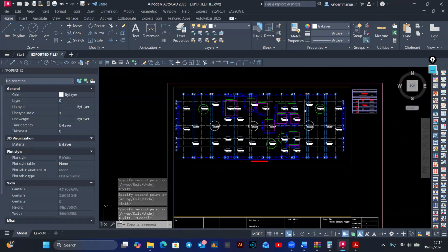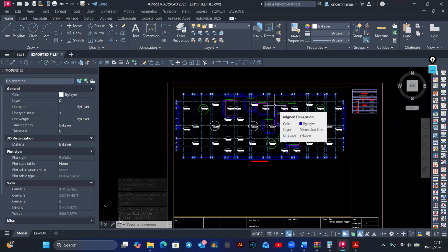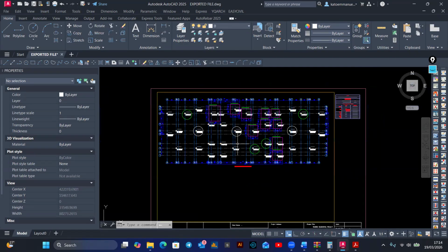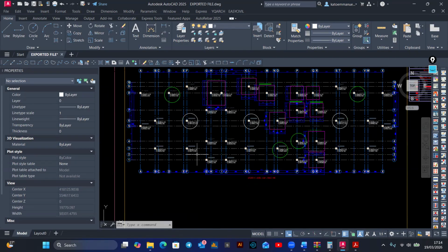So when you are designing your footings in ProtaStructure, you do not design all the footings for the entire structure. You look out for the axial loads that you have grouped. For example, this is green, green, green, green. You look among the greens for the column with the maximum axial load. That is the one you identify and design that footing. Then you assign that footing to all those which are green. You get it. Likewise, you go on grouping all the other columns like that.